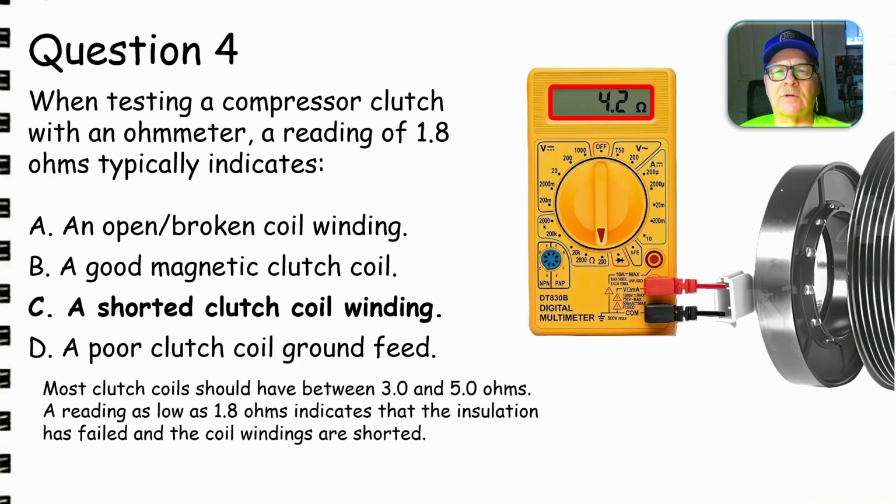A lot of the times we don't even think about how many ohms that thing is supposed to have. Typically these things, when they short out, they'll start popping fuses. This friend of mine has a shop. Somebody brought him a 2006 Impala that would blow the fuse for the compressor clutch. And so he investigated it. The compressor clutch was still working, but it was pulling too much current because it was only partially shorted.